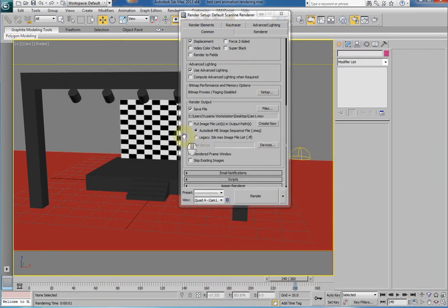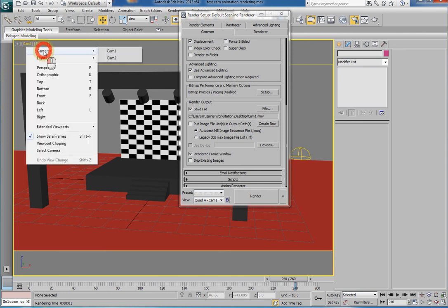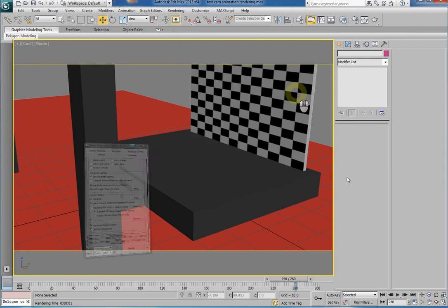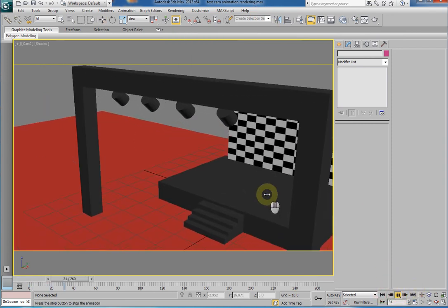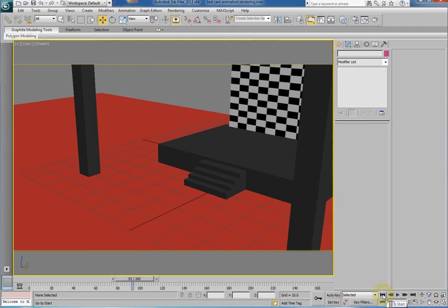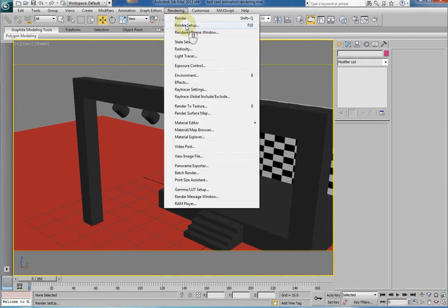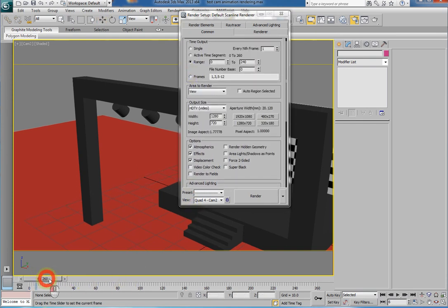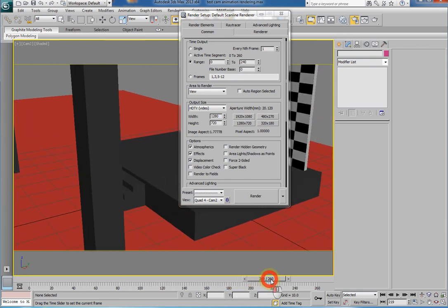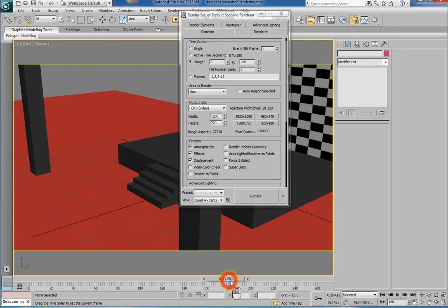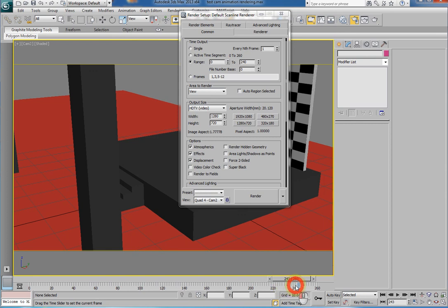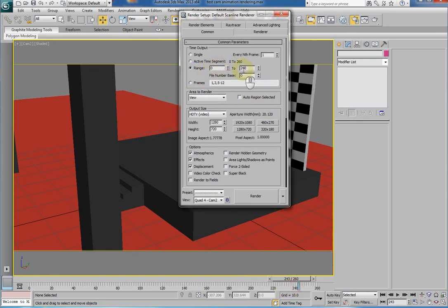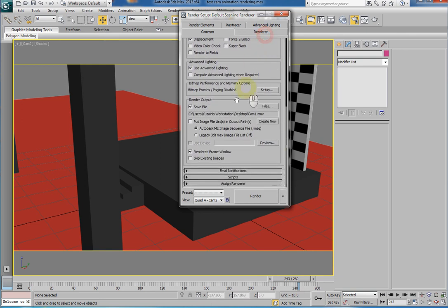For the next step, once your render is finished, you can continue rendering the other cameras, which is camera 2. So our camera 2 is like this. We're going to render this out. Go to render setup again. The only thing we need to change is 2 things. For example, we need to determine where it should stop. Let's say same 240, so we don't have to change the range. We will be ending on 240 frames. Then scroll down to the output.